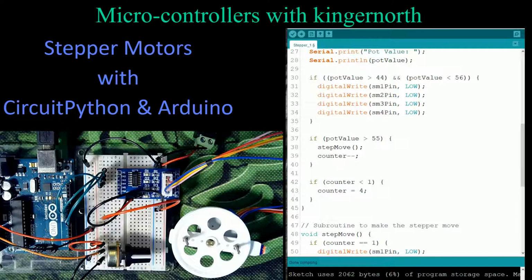So I'm just going to set it so it's rolling through there. So I subtracted 1, I went to 0. Well, I can't set the pins based on counter 0, but 4 would be in that direction. That's going down. It's going to loop around through the set. So that way it will go to 4, and it'll go to 3, to 2, to 1. It goes to 0, so it resets to 4 and continues on. So that's how we fix that.